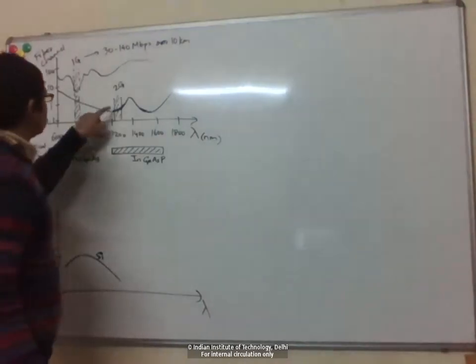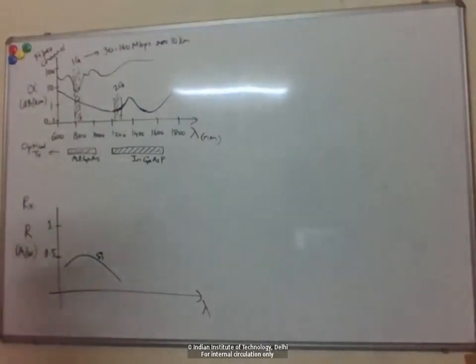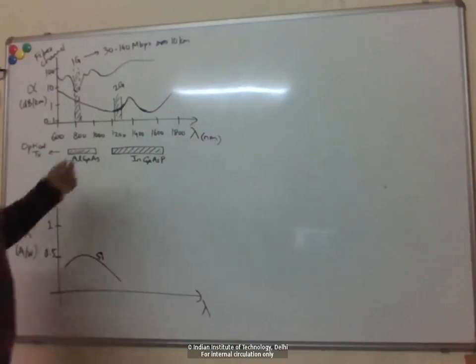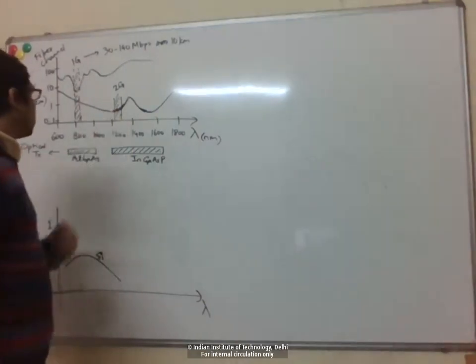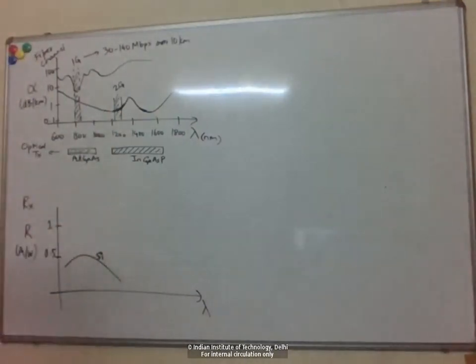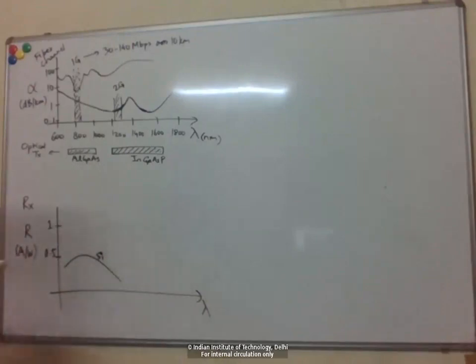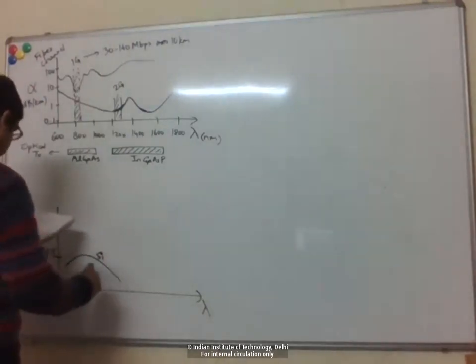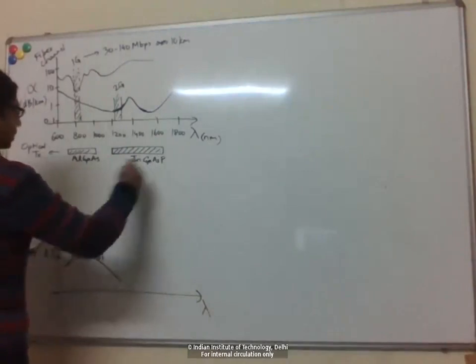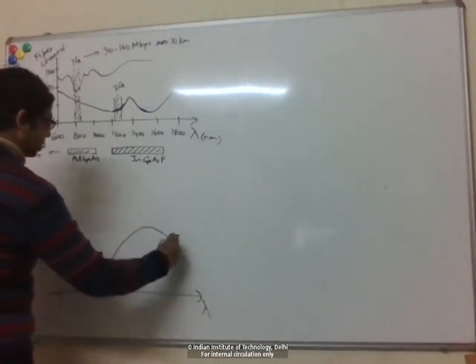Another reason why people went for the 1300 wavelength was, as you know, we are not plotting dispersion here, but people who have done the fiber optics course know that for silica fibers, the dispersion crosses zero around 1300. At these wavelengths the dispersion is also very low, so you can send optical pulses over long distances without them broadening too much. In terms of detectors, a similar kind of technology was used. They are called InGaAs detectors.